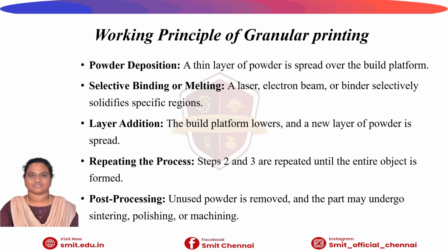Finally, the post-processing. Once the printing is finished, the unused powder is removed and reused. The printed part may then undergo sintering, polishing, heat treatment, or machining to improve the strength and surface finish of the material products.